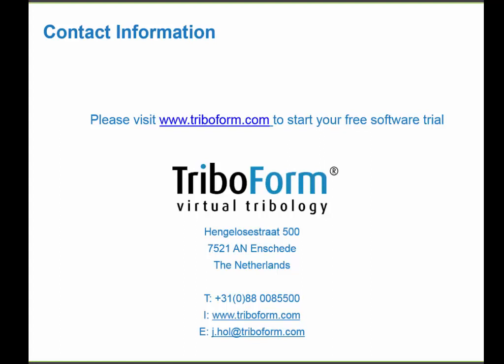I myself have to say that I was very pleased to see that you had announced the release of the software a few months ago when we invited you initially to join, because that was always the biggest lingering question that would come from customers who I have trained how to use AutoForm: what do I put in for friction? We would tell them that 0.05 is sometimes a conservative number, but we also see that sometimes 0.15 is not conservative enough.